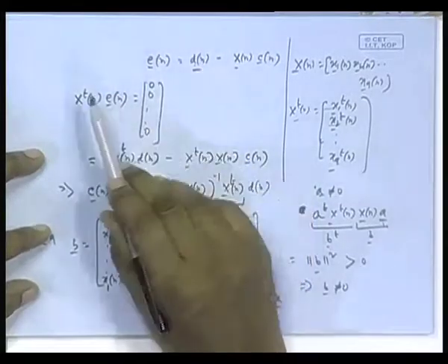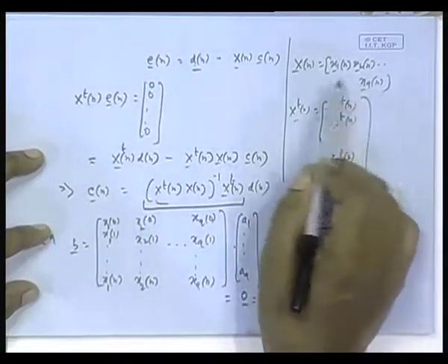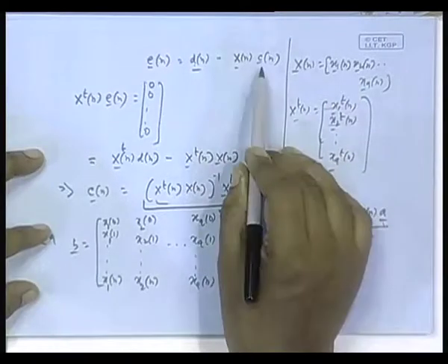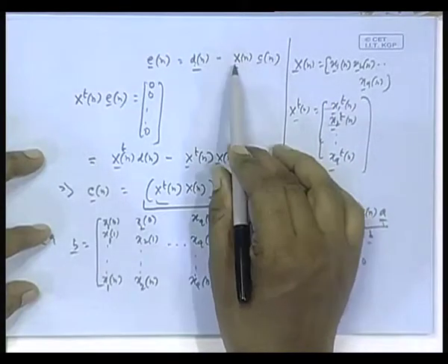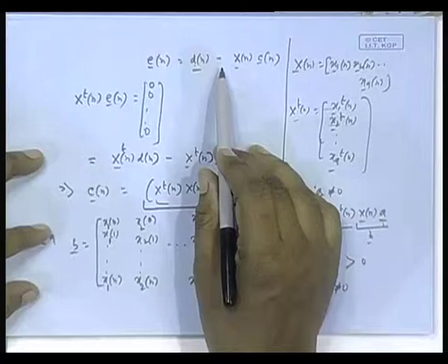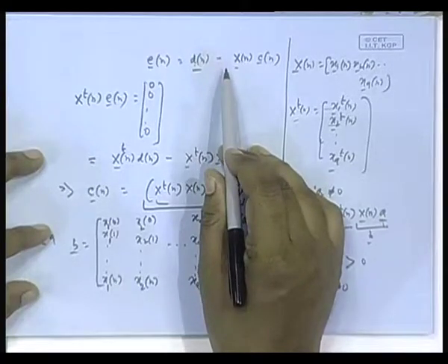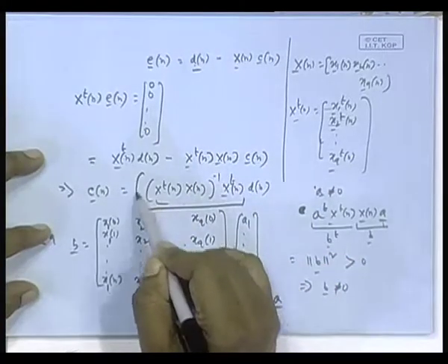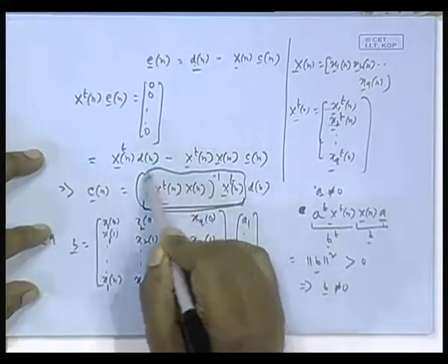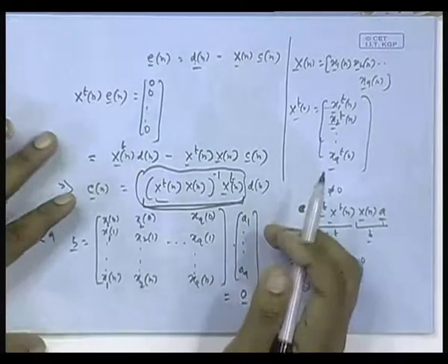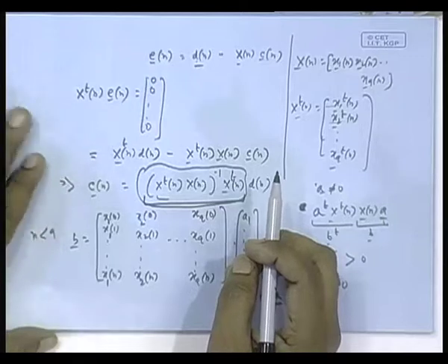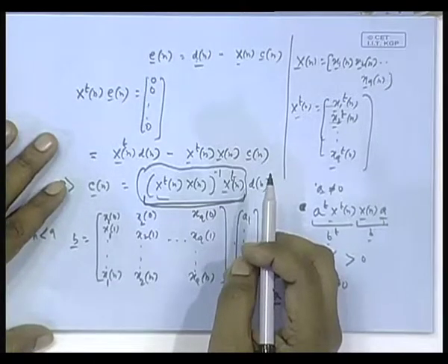Otherwise, if dn is outside the column space of this matrix, then you will get that combiner coefficient which will give the minimum error norm. This matrix working on dn is called the least squares inverse, or more popularly the pseudo inverse of the matrix xn.